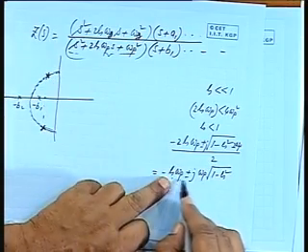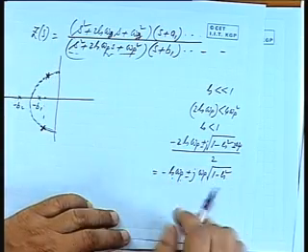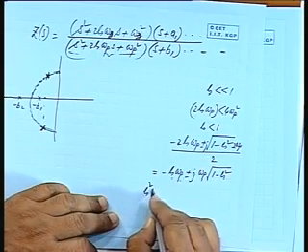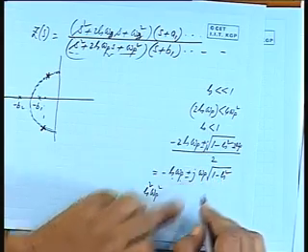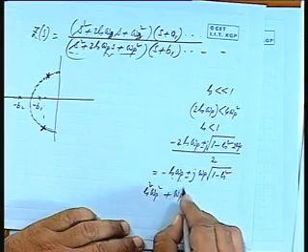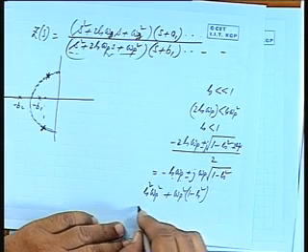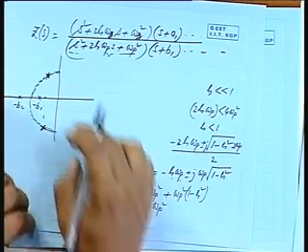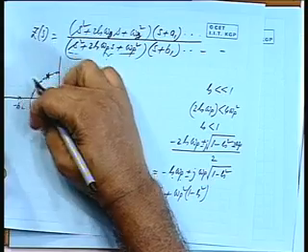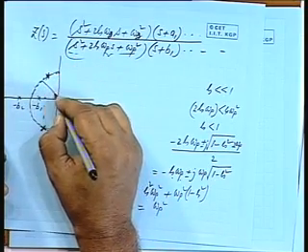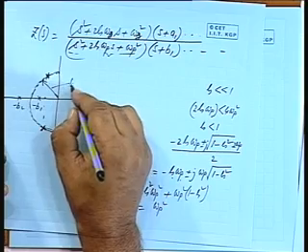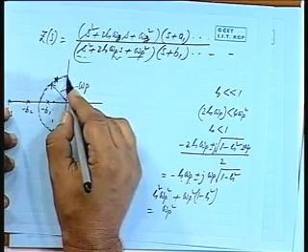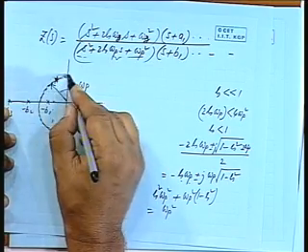Now, you see the real part squared and the imaginary part squared, if I take, that is constant. Real part squared is zeta square omega p square. The imaginary part square will be omega p squared into 1 minus zeta square, and the sum is equal to omega p square. The zeta-dependent terms cancel. That means with omega p as the radius, if I draw a semicircle, then for different values of zeta, the roots will be lying on this semicircle.